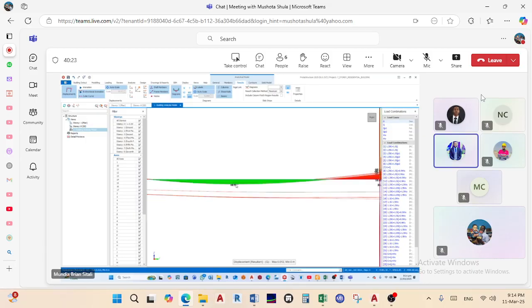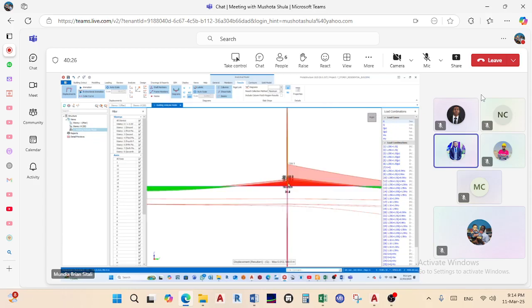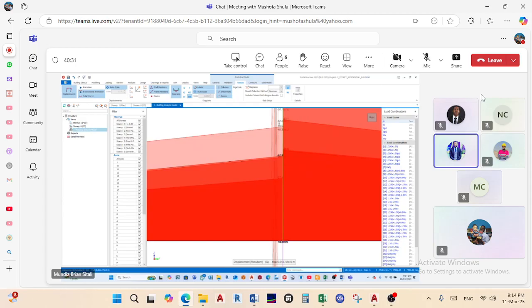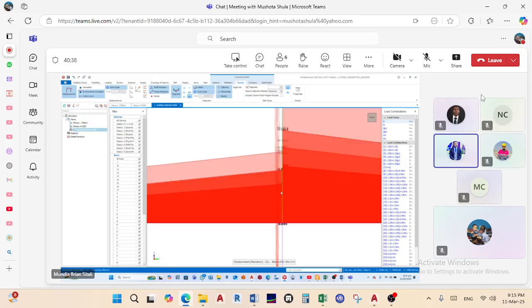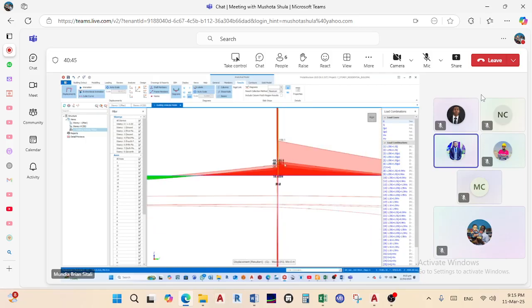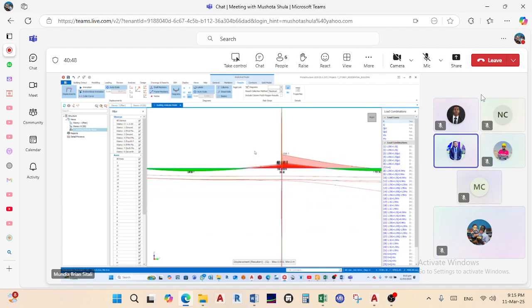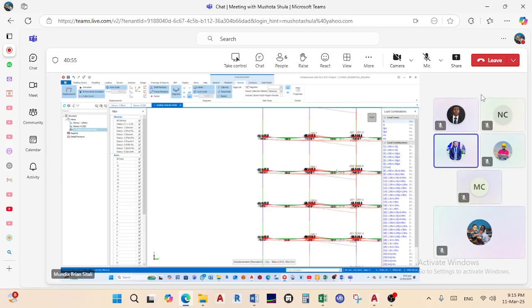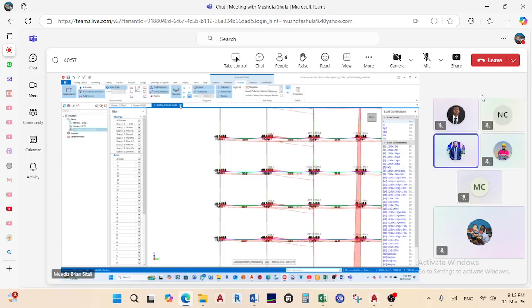I want to see what moments and shear forces are active in this zone, where the concrete ends and a steel connection comes this way, so that when I'm doing some work outside, I'm able to. You can get all that information from here after you're done modeling. For now, we're doing everything within this, so it will automatically work itself. Okay, so we can close that.